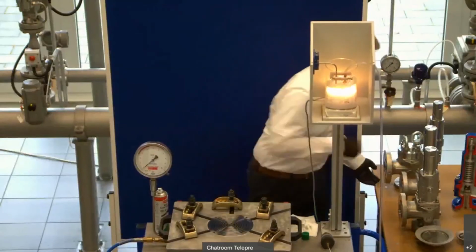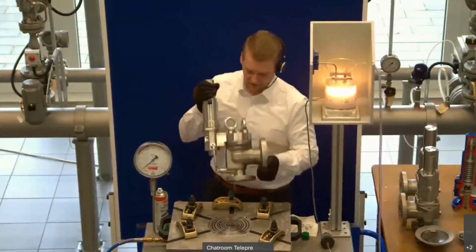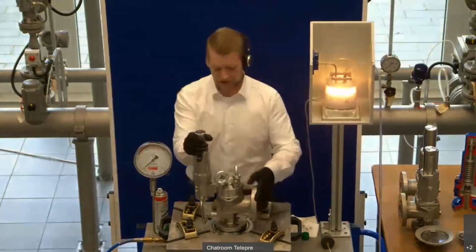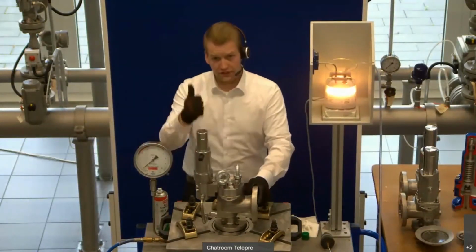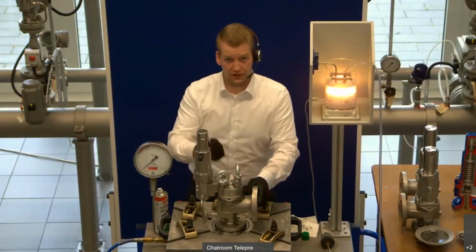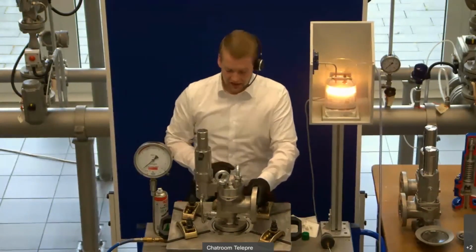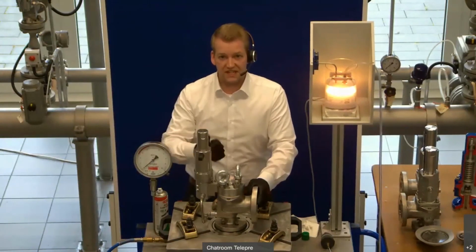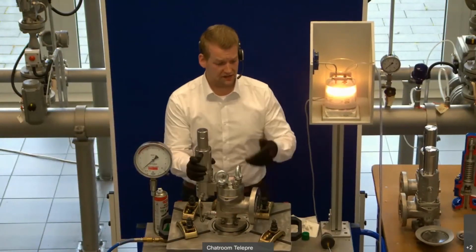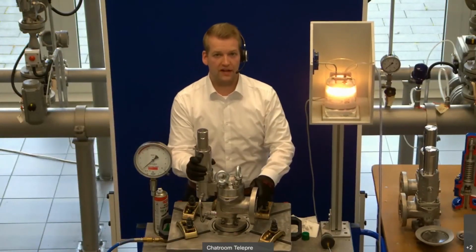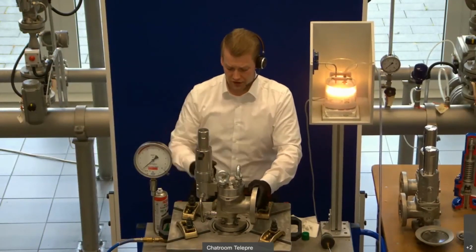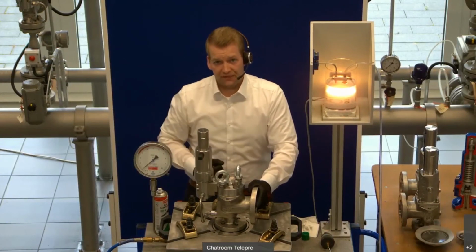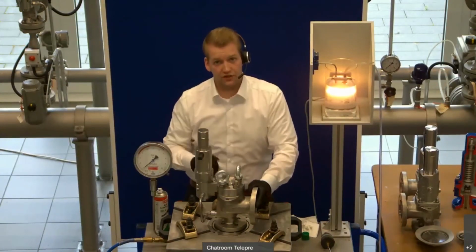Here we see the pilot operated safety valve, the modulate action, and have a look, the first step was to set the CDTP. Then we have to do the seat tightness test. This is in this case the same. We do the bubble counting method. And for the bubble counting method, you go directly to the test pressure, and the test pressure was 90% of your set pressure.